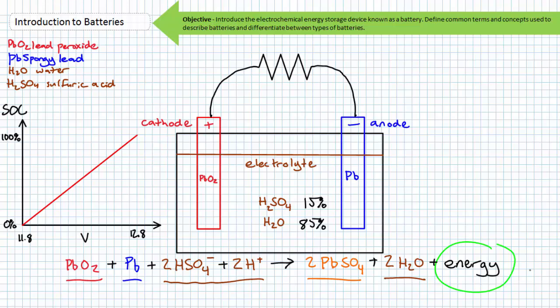A nominal 12-volt battery might have a working voltage of 14.4 volts during one stage of the charging process, an open circuit voltage of 12.8 when fully charged, an open circuit voltage of 11.8 volts when deeply discharged, and might even drop to a working voltage of 10.8 volts when delivering a brief but intense burst of current, as in when a starter battery is used to start a car.